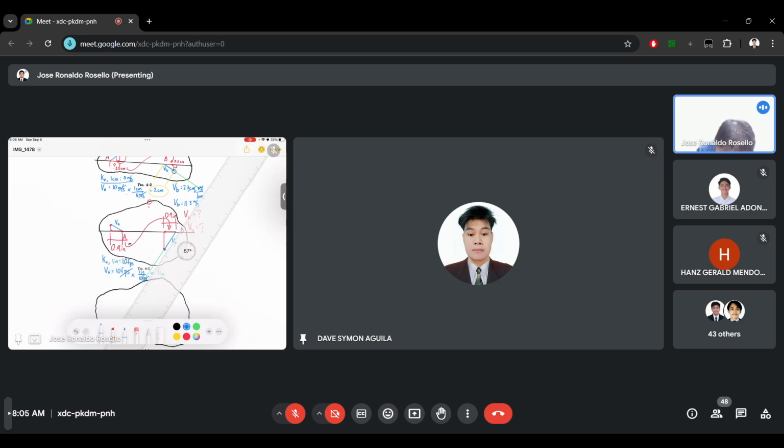Okay, so let's measure it. How long? 1.6. So if our measured velocity b is 1.6 inch, we can compute again using the velocity scale. The velocity b is equal to 1.6 inches times the velocity scale, which is for every 1 inch, we have 10 feet per second. Cancel inch, and we will have 16 feet per second.